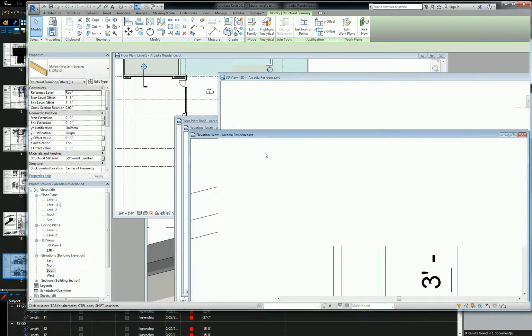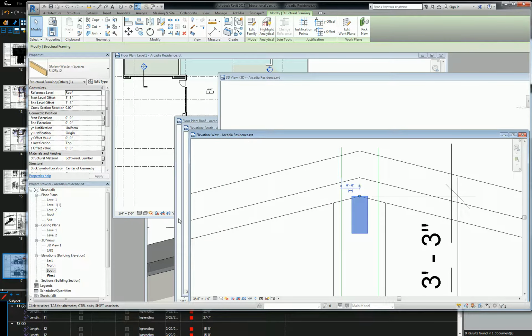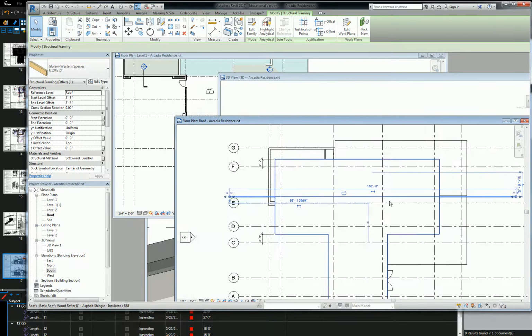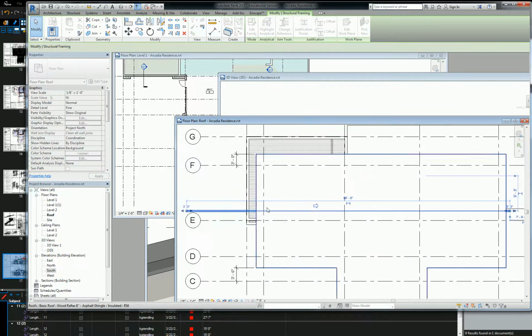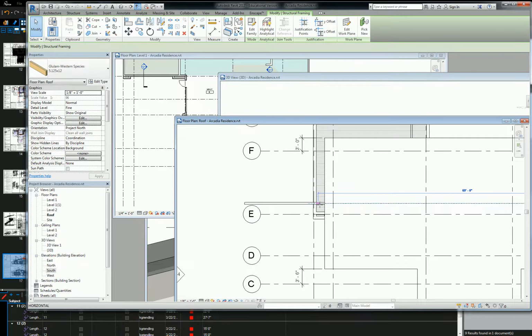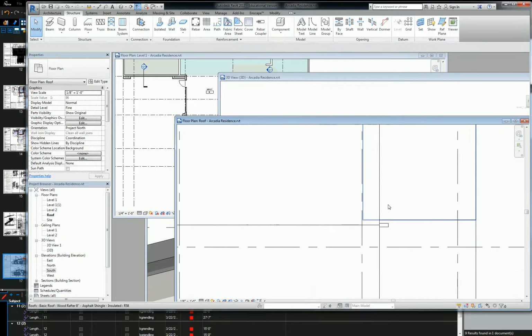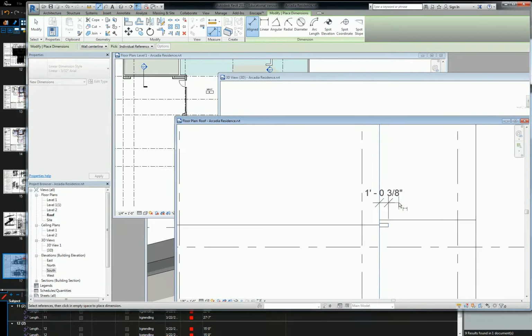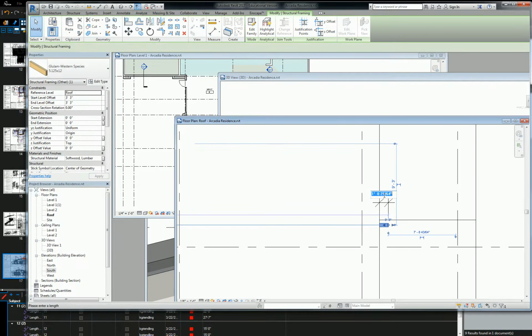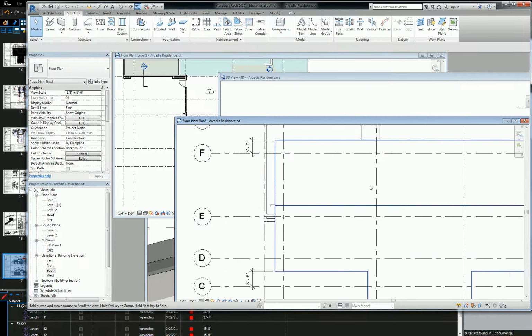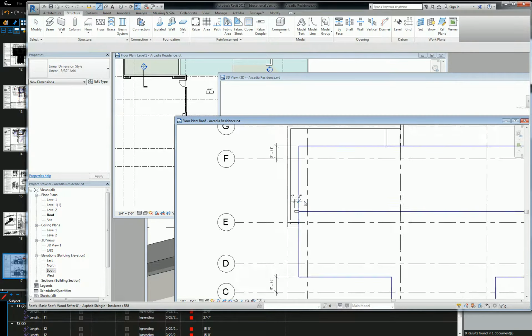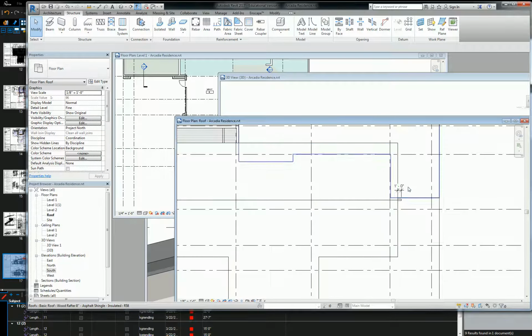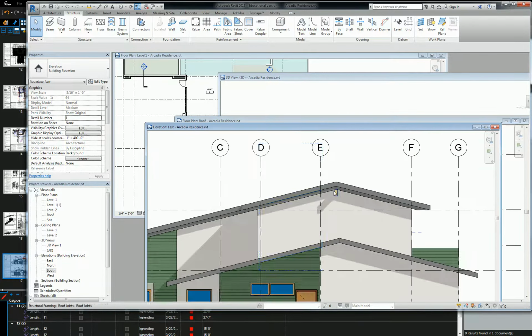And then lastly, we are responsible for, in the roof plan view, making sure that these extensions only go so far. So if you pull the grip back to about this far, you can put a dimension on it and just make sure that it's only a foot. So we'll pick this and say 1 foot. And then we'll do another dimension on this side, there to there, 1 foot. Okay, so I just double check that. I don't need to know the exact dimension anymore after that. All right, so there's our beam.